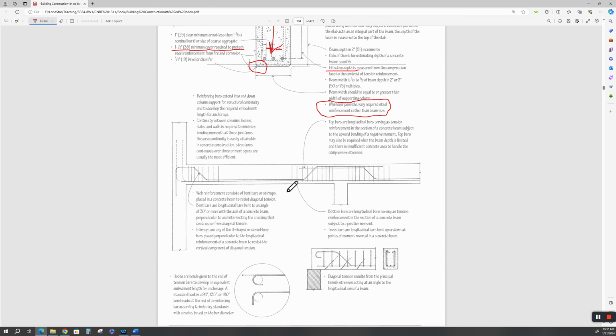This doesn't have much to do with you architects, okay? But it's a good representation of the problems we get into as structural engineers and contractors, for some of you who may go into construction management. How are we going to get all this extra reinforcing steel at this rigid joint? Remember, this is a rigid cast-in-place joint, all right? How are we going to get all that concrete around that reinforcing steel? Some designers will put so much reinforcing steel in there, you can't get the concrete around it. We've got to back up.